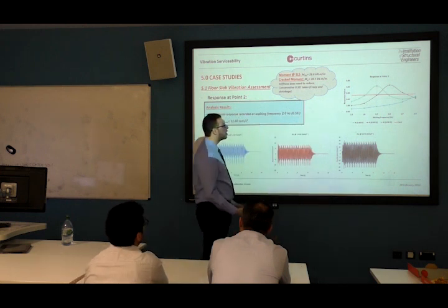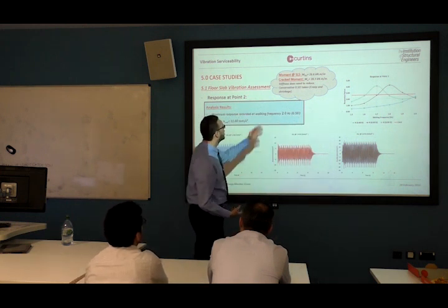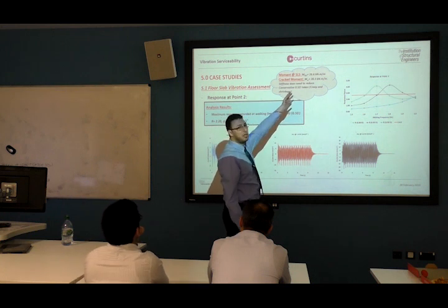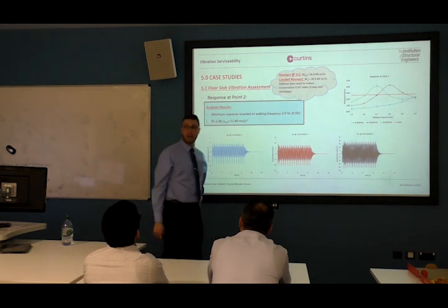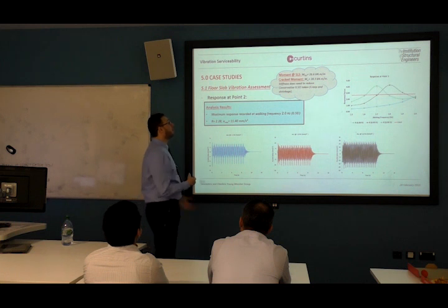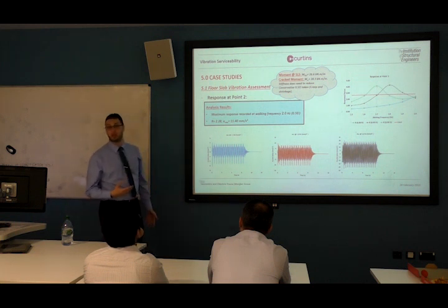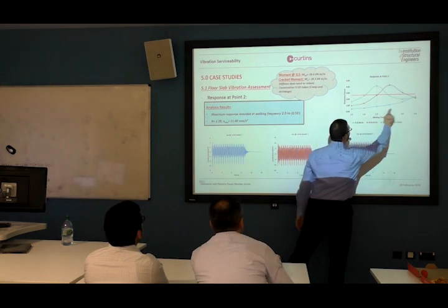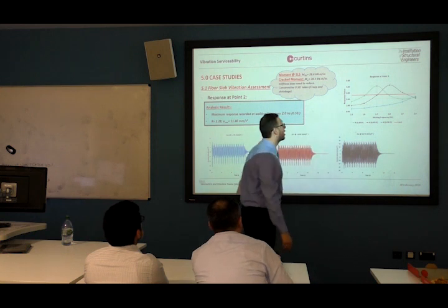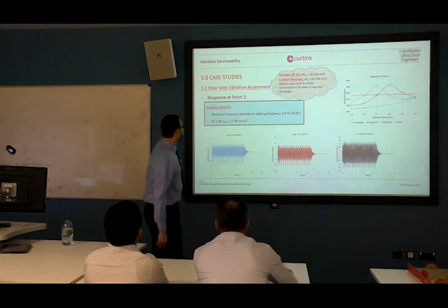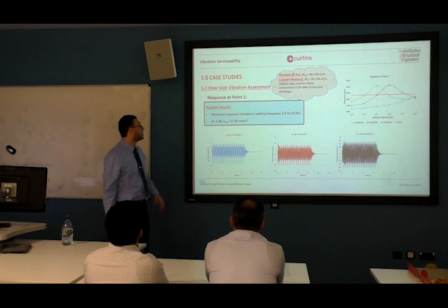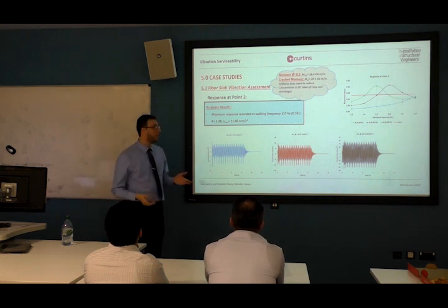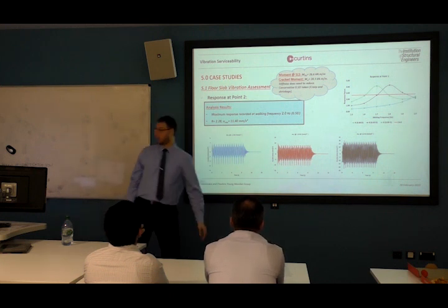But we said we don't actually have to crack it because the SLS moment was about 26.6 and the cracked moment was about 28.3. So it's actually not cracked. I would say we're going to crack it by 50%, and when we cracked it by 50%, this is what we had. The maximum response was about 11.4 millimeters per second, which is 2.2 as response factor, and it was alright.